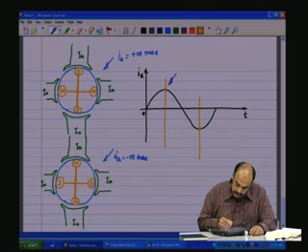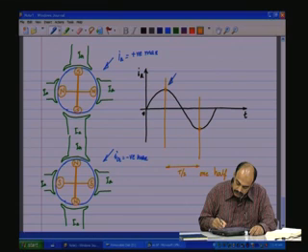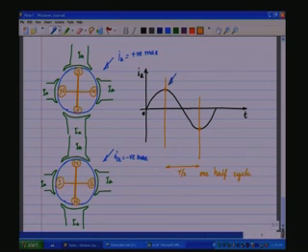However, here you have one complete half cycle, T by 2. That is one half cycle. So one half cycle makes the MMF rotate by 90 degrees, and to get 360 degrees you need 4 half cycles, or 2 cycles, to complete one complete revolution of this one.